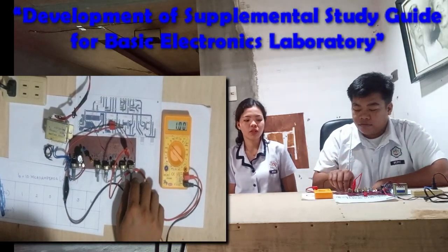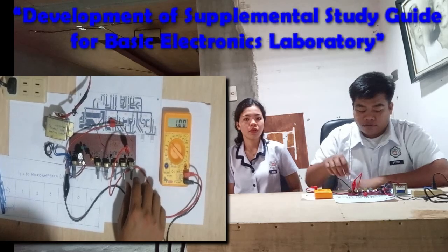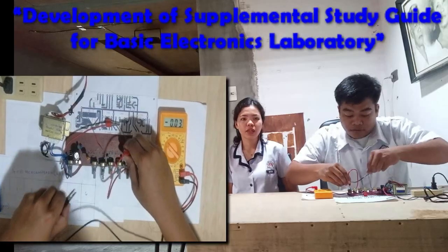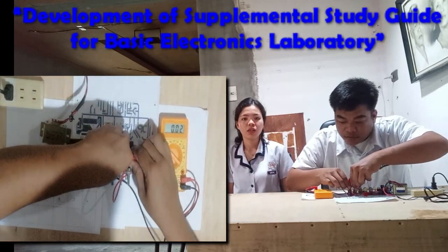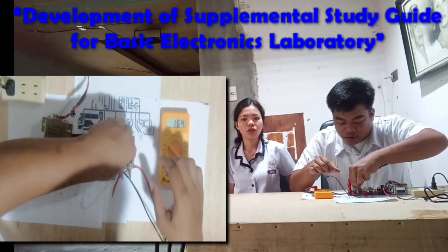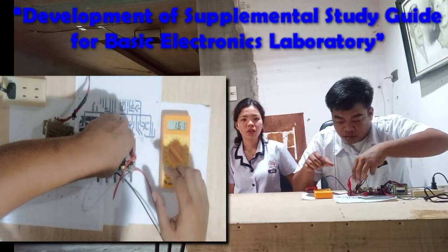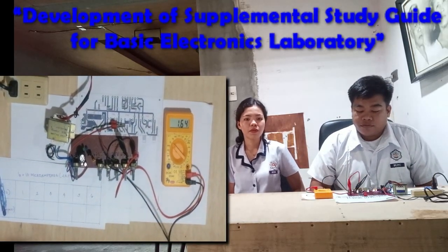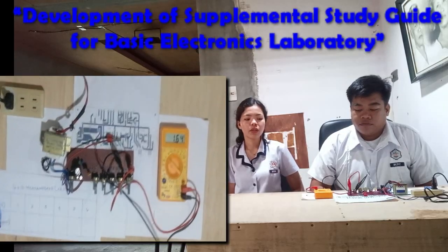Use this voltage measurement and the resistance of R3, 1000 ohms, to calculate the current flowing through R3. Since R3 is connected to the transistor's collector lead, our calculated value of current also represents the collector current flowing through the transistor.